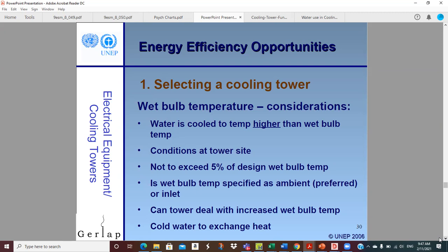So you have to be careful, because what you really want to size your tower for is the wet bulb, the moisture level of the air that's going to be going into your tower at the location it's going to sit. And so you may have this wonderful weather data file that was compiled at a station 4 miles away, but you're sitting on the lake and your weather conditions are actually different, especially the amount of moisture in the air is considerably higher because of where you are.